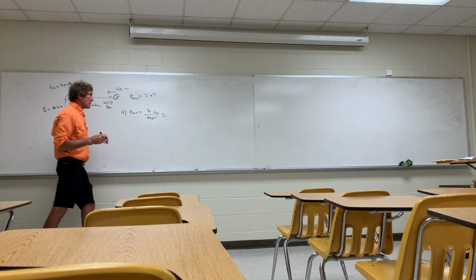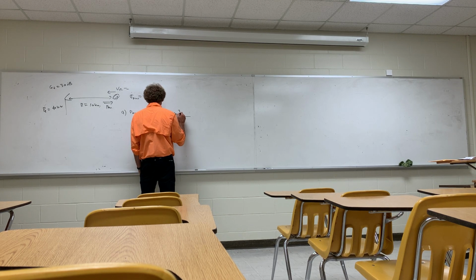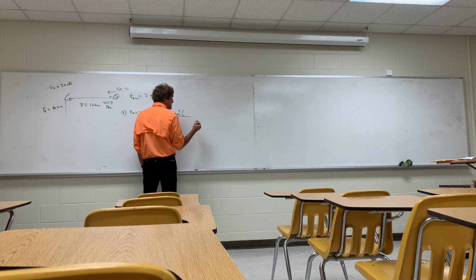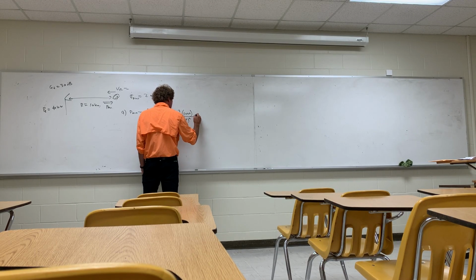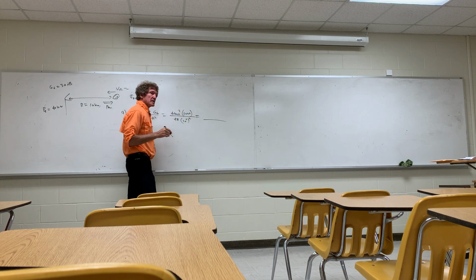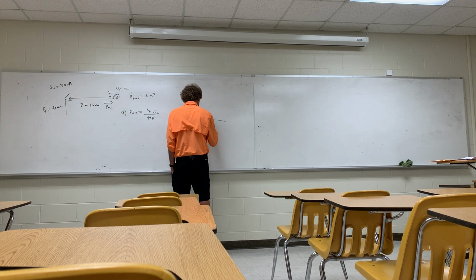Yes, sir. All right. So this is going to be 40 times 10 to the third times the gain of the transmitter, 30 dB, or it's 1,000, over 4 pi, and then R is 10 to the fourth, and you have to square that. It's a straightforward calculation. Can somebody do that? 31.838 kilowatts per meter squared.